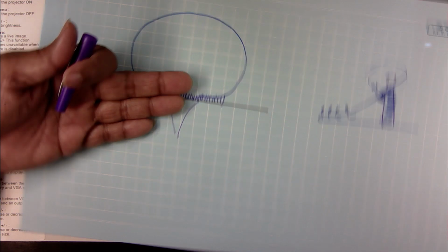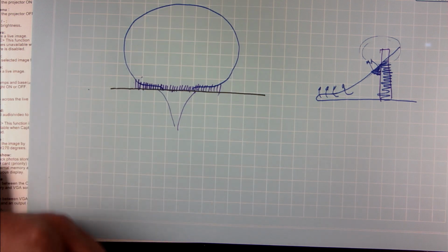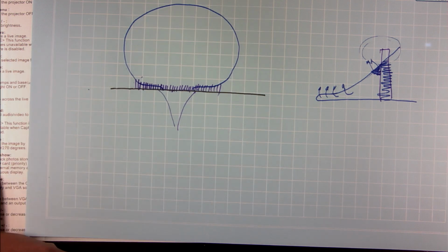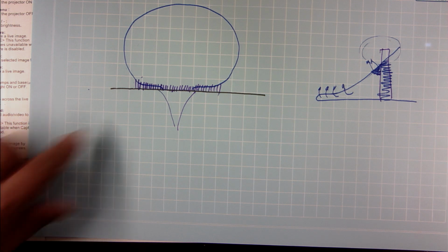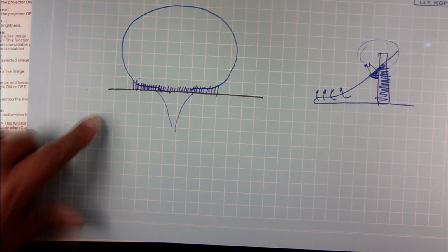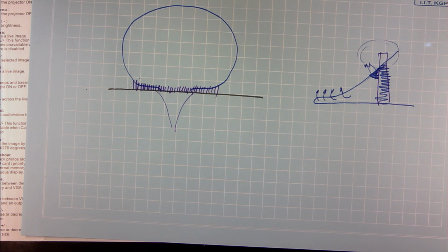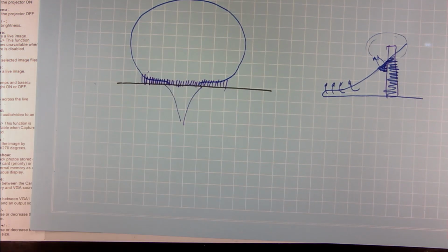And so, there is another theory in boiling which I did not get to discuss, which is known as the wickability theory. According to the wickability theory, these nanofins serve as a porous surface. What Dr. Bhattacharya is going to describe in the afternoon is microporous boiling, but these nanofins effectively have formed a nanoporous surface.